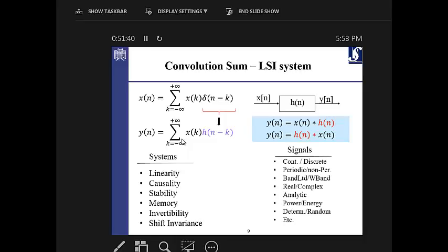But when I say it in a different sense or a more general case, it's not as easy as you think here. Sometimes they go through the dictionary that the signal is made from. They make an over-complete dictionary, then using regularizers and some prior knowledge, they try to extract those atoms of the dictionary from which the signal is most likely to be created. And that differs from one frame to another. So that's why it's not just as easy to say, okay, I found the inverse of the system. No, it's not the inverse of the system. It's the best approximation of the system for that moment.